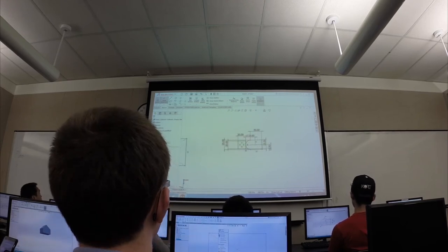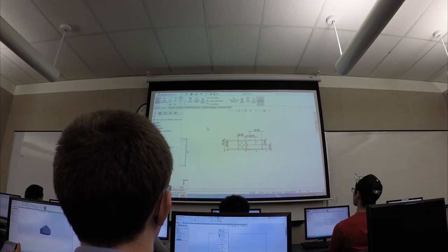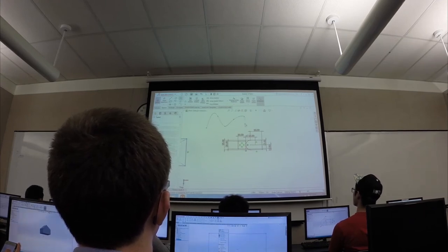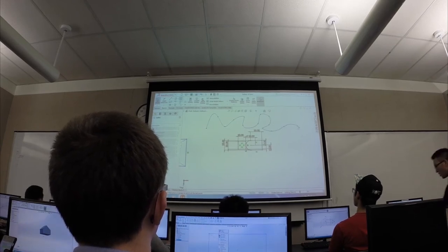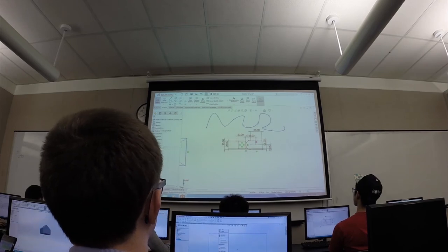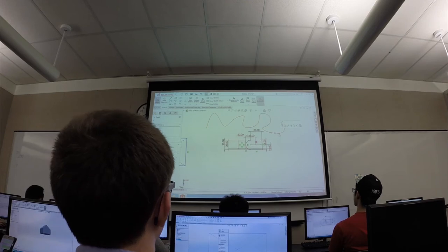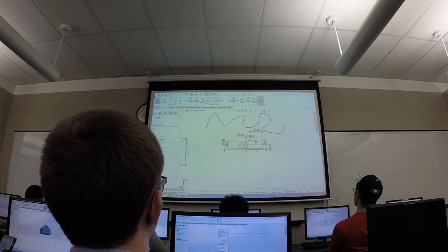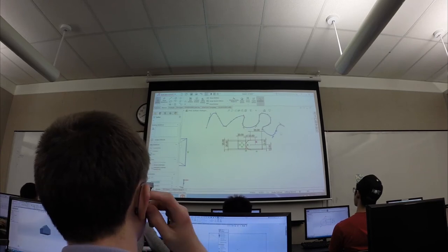Cool. So we got to play around with some of the entities. There are things like splines. This is kind of cool, in the sense that you can start drawing random squiggly lines. You select points that it wants to be on, and then you can start defining its curvature. We're not going to play around with it too much, but it's something cool to show. You can start dragging these points, and there are little arrows where you can define the length of it and the angle it goes at. This allows you to make complex curvatures in your designs.